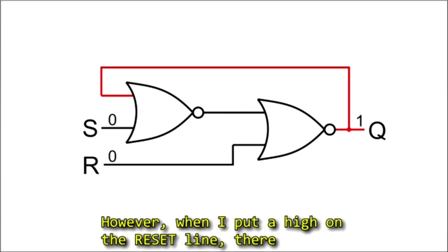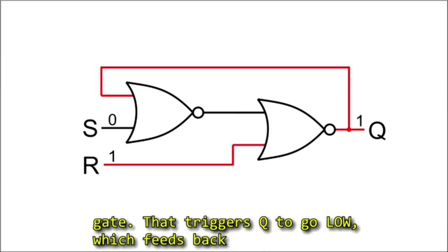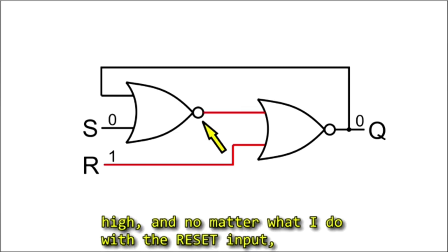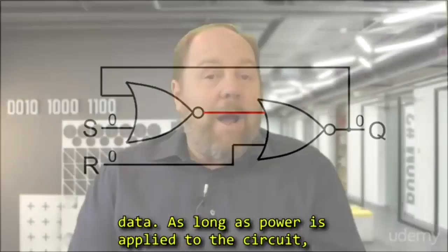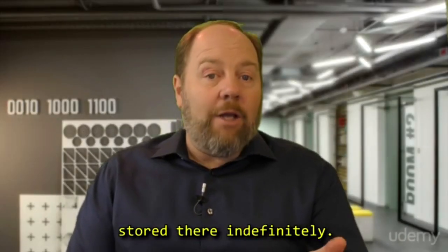However, when I put a high on the reset line, there is now a high on one of the inputs of the last NOR gate. That triggers Q to go low, which feeds back to the first NOR gate, which now has a low on both inputs. The output of that NOR gate will now go high, and no matter what I do with the reset input, Q will stay low because of the feedback. So as you can see, we can use a flip-flop to store one bit of data. As long as power is applied to the circuit, it will hold whatever value we last stored there indefinitely.